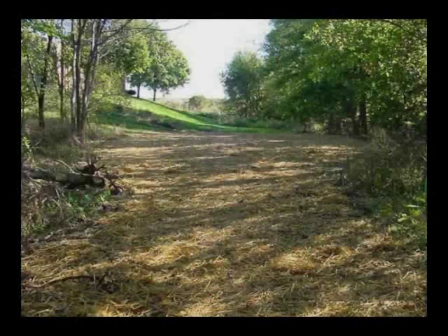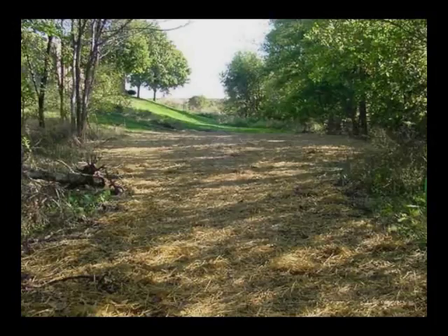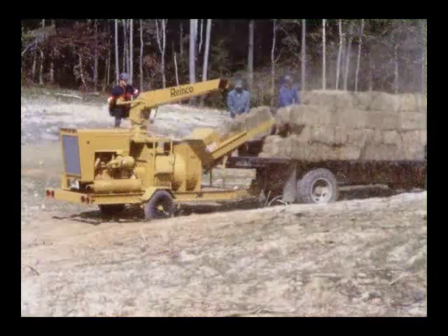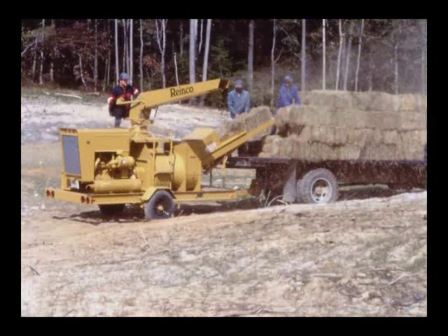Mulching is essential when establishing grass or other vegetation from seed. Mulching involves placing materials such as straw over the seed to protect the soil from erosion and to provide a proper environment for the germination and growth of vegetation. Mulch insulates the soil from intense heat and cold and conserves moisture by limiting evaporation. Mulch can be applied by hand or with a mulch blower.